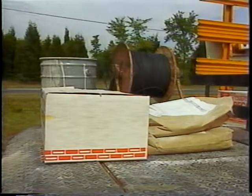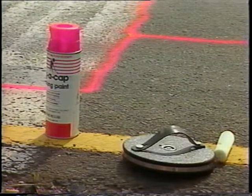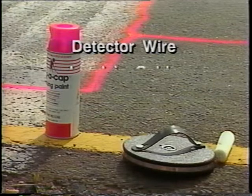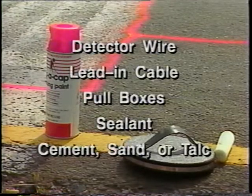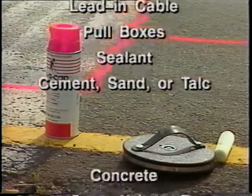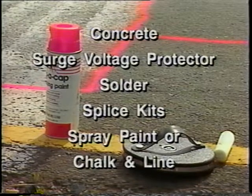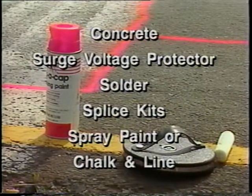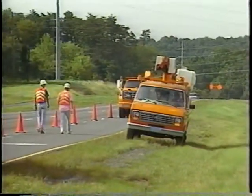any work interruptions. A typical material list for a loop installation includes detector wire, lead-in cable, pull boxes, sealant, cement, sand, or talc, concrete, surge voltage protector, solder, splice kits or equivalent, and spray paint or chalk and line. This completes the pre-installation process.